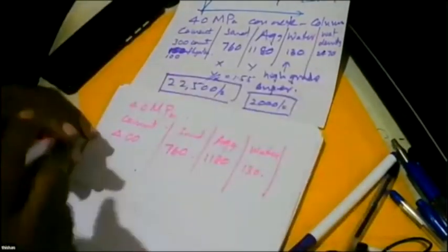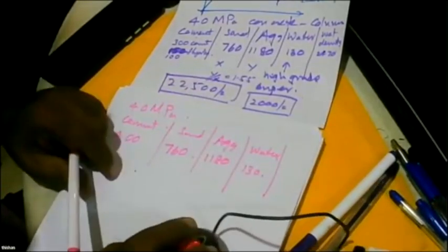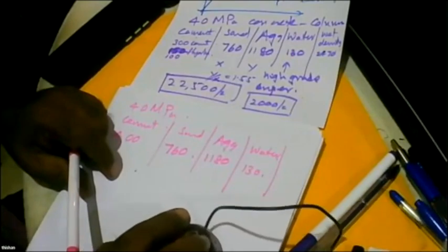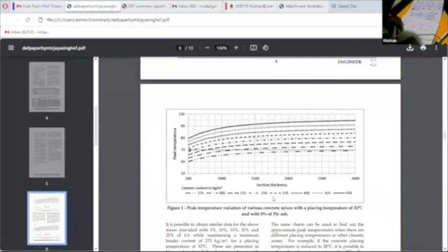Okay, first difference. I'm going to share the screen now. Look at this chart. So you are having 400 cement. That is 1, 2, 3. Here, you don't know anything about DEF. What is the size that you can cast? The maximum size you can cast is about 400 millimeters. Is that clear? Without any risk of DEF, what is the maximum size you can cast?